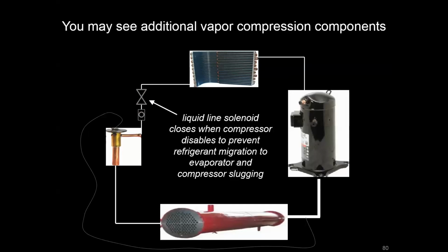Next, you might see in that area a solenoid valve or something that looks like this, and that's essentially an electromagnet or electromechanical valve that is going to isolate this line. So it's essentially a binary open and close, and what it's going to do when energized is just fully open, let refrigerant go through, but when the compressor's off and the system's off, it's going to fully close.